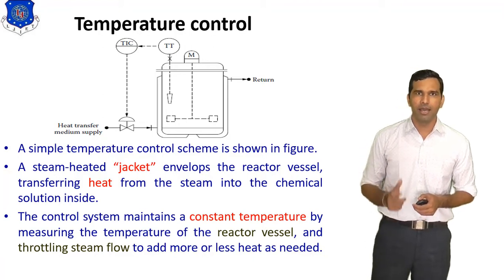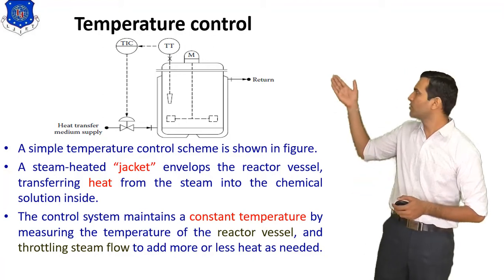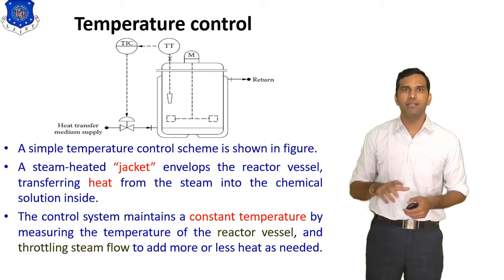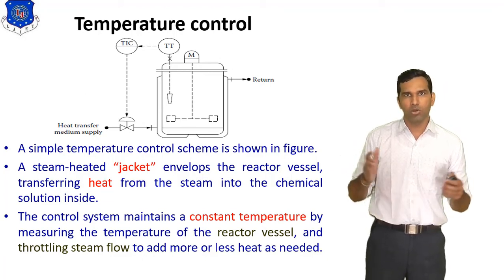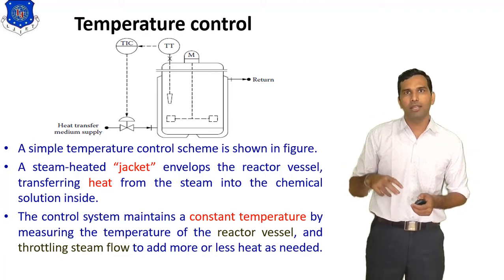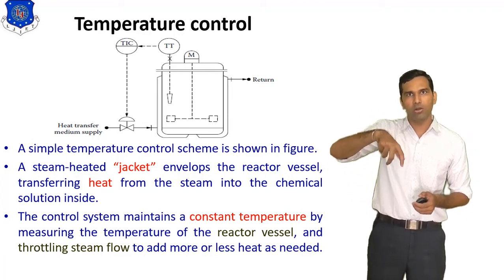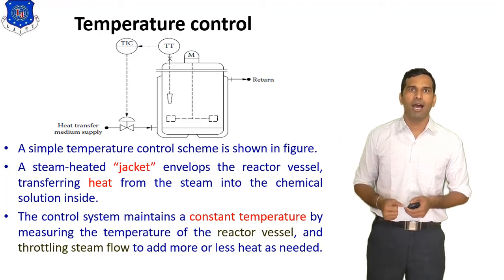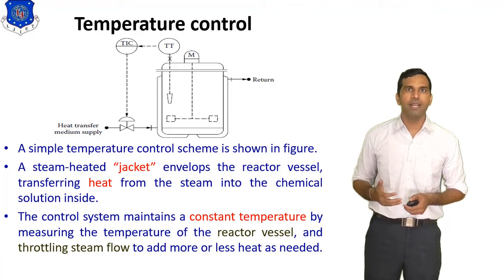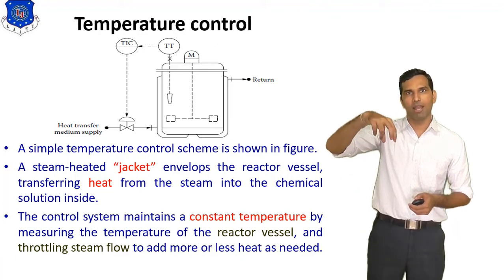Here, this is the temperature controller, which maintains the temperature inside this closed vessel by throttling, that means opening or closing the valve. If we require more heat, it opens the valve more.